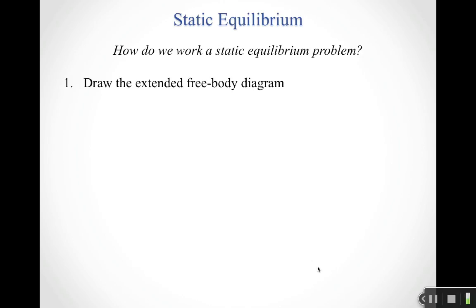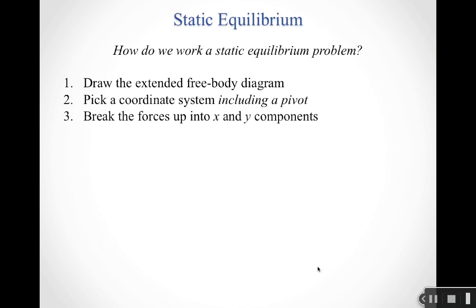So what's the process that we're going to do? Well, we'll start the same place we always do by drawing an extended free-body diagram. That extended free-body diagram will let us show not just the forces that act on the object, but where they act. Then we'll pick a coordinate system, and here we're also going to need to pick a pivot point. So what's the point that we want to use to do our torque calculations from? Then we'll break up the forces into their x and y components,